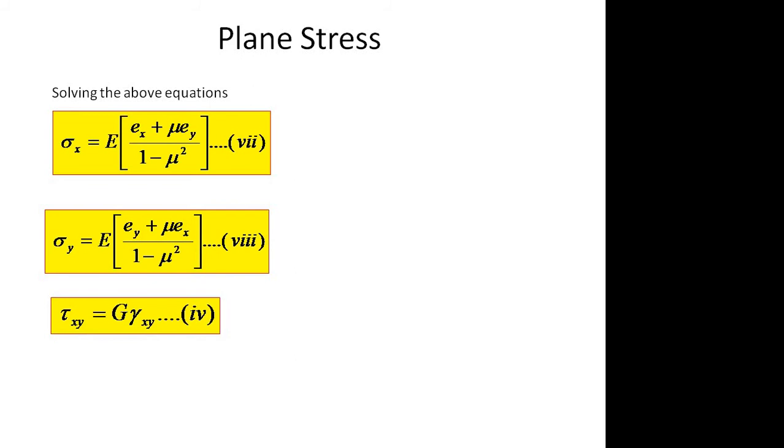At the same time, we can measure the end effect, that is the displacement. But measuring the stress is very, very difficult. So we have methods for measuring stress, but it is very, very difficult. So what we do, we measure the external loading and we measure the displacement and then convert it to strain components, and from the loading and strain we calculate the stress.